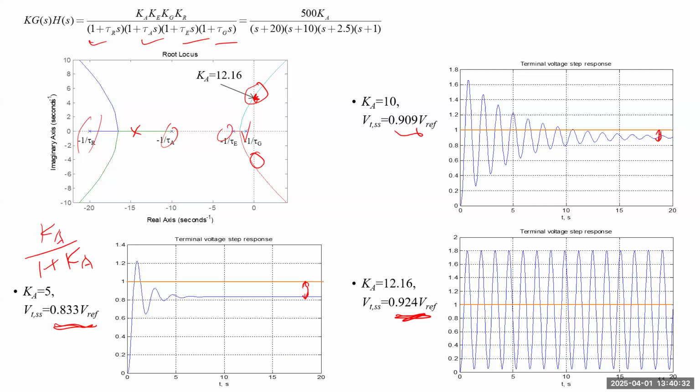Those rules can still be applied, so that will change the angle and direction. For instance, if you add an additional pole, that can make this root locus point more in a different direction. That gives you additional room to use an even bigger gain without losing stability.